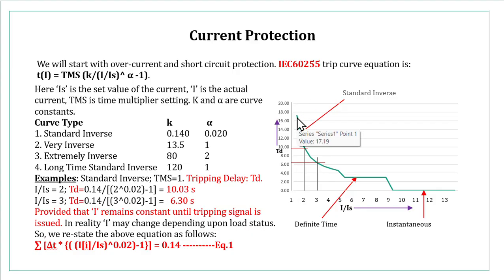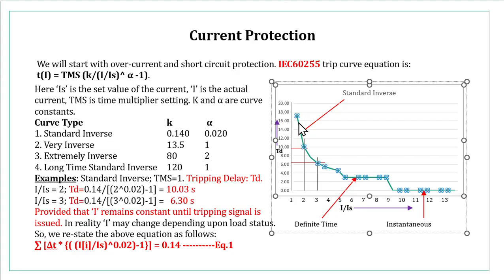This is logically okay. So you can see here these parameters. This shows 0.1 in the inverse characteristic. This shows the second point, which is still 0.03. This is the third one. It is 6.30. Then comes 5.52 when I upon IS is 4. Then this. So like that you can see that at 5 times the overcurrent value, you get this. So like this it goes on.